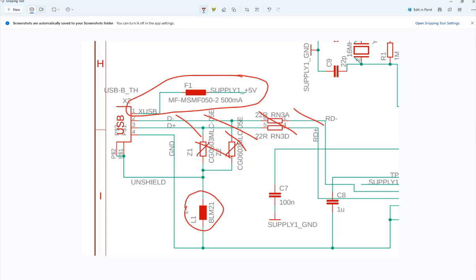And this is an inductor. Inductor is rejecting what? AC noise. Is an inductor a good component to be placed between your chip's ground and the global ground? Yes. Why? Because ground is DC. Good. It's rejecting what? AC noise. But passing ground DC, so you are getting a solid DC ground without any problems.